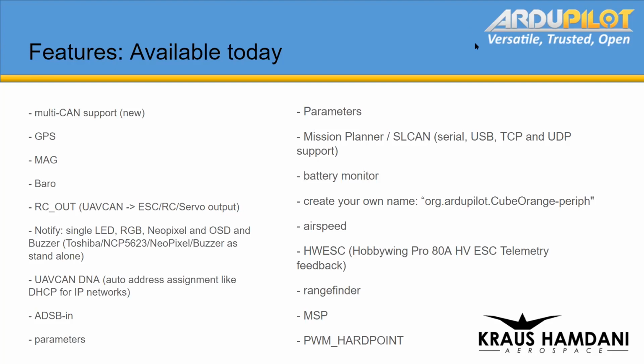Yeah, in fact, I added that to the UAVCAN spec. I think I renamed it, but at one point it was called tunnel. So you could tunnel just bits, and so you can make it be SPI or I2C or whatever data you want over that tunneling. I think they call it bridging now or something like that, but yeah.